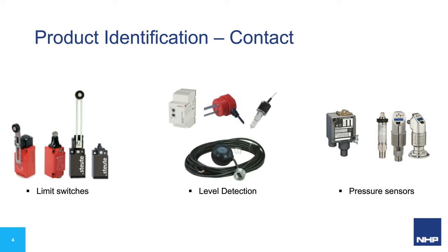Next after that, we have electronic and electromechanical level detection. The electronic versions are at the top, and the first device after the relay uses conductive level detection using the stainless steel probes with the level control relay. To the right of this is a non-conductive level detection device using the photoelectric level sensors with a level control relay. Below that is the electromechanical version, which is a more simple device, a basic pre-wired cable with a float device and a counterweight.